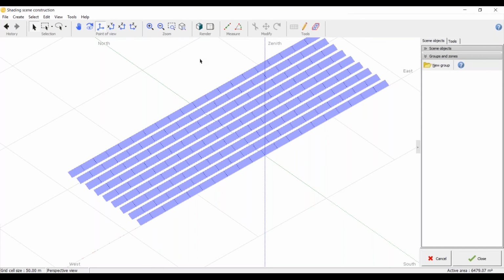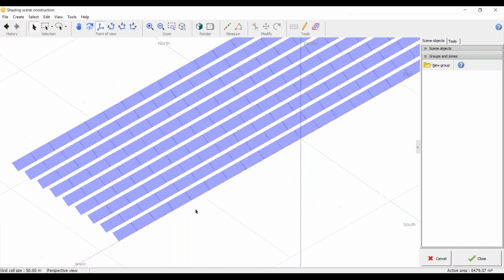Whereas when you don't have a partition within PVSyst, PVSyst assigns the shading loss to the entire system. Let's say you have a 20 kilowatt system, and the upper row is comprised of a 10 kilowatt string and another 10 kilowatt string. So only one 10 kilowatt string is getting shaded. So the whole system would still be producing 10 kilowatts worth of energy every single hour, depending on the sunlight and things like that, right? So that is what we could be simulating with this.